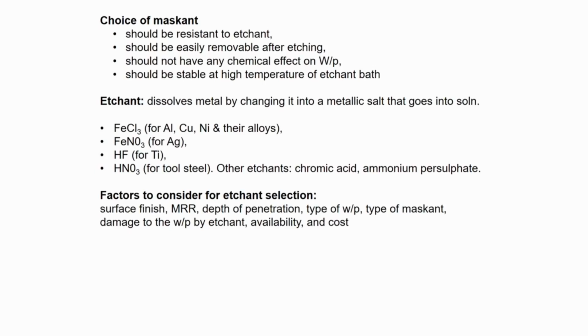Factors to consider during etchant selection: surface finish, material removal rate (how much is required), depth of penetration, type of workpiece, type of masking, damage to the workpiece by the etchant, and availability and cost also matter while selecting the etchant.